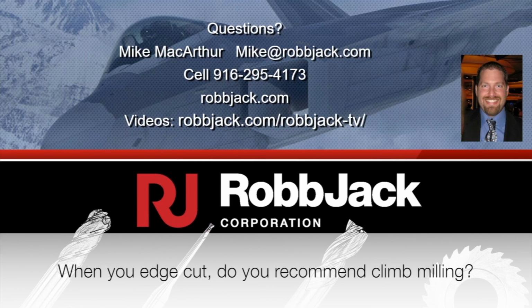I would say we recommend climb milling about 95 to 98% of the time.